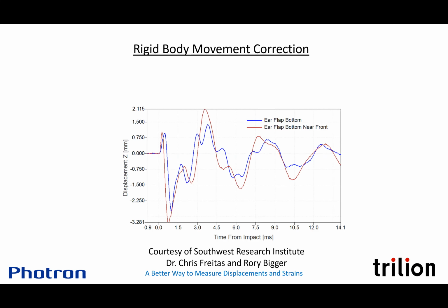We can co-calibrate the IR camera to the Aramis stereo pair. So we can map the temperature from each pixel of the IR camera onto each data point in the DIC software. And then we can even do a correction. We can subtract out the thermal component of strain and leave only the mechanical component of strain.